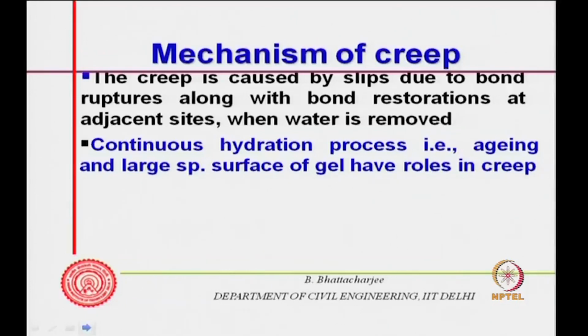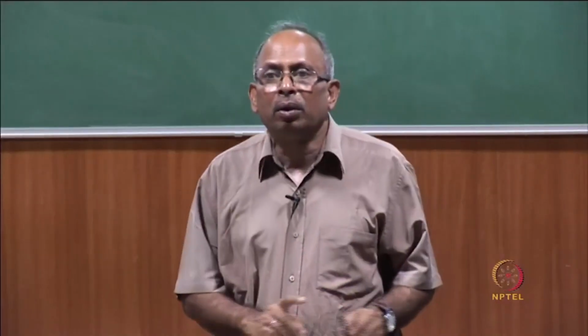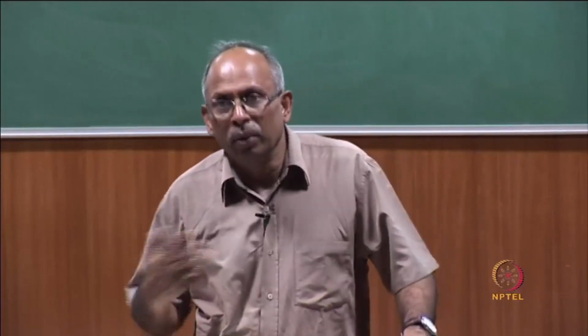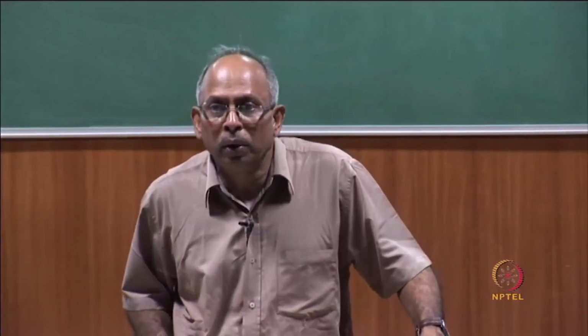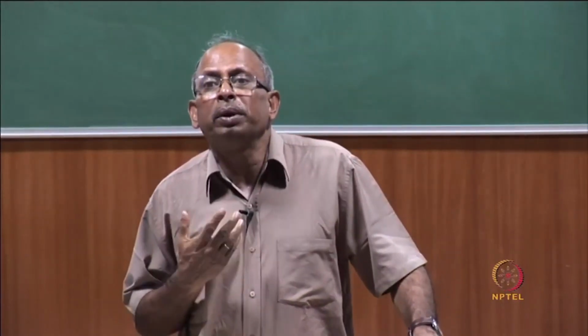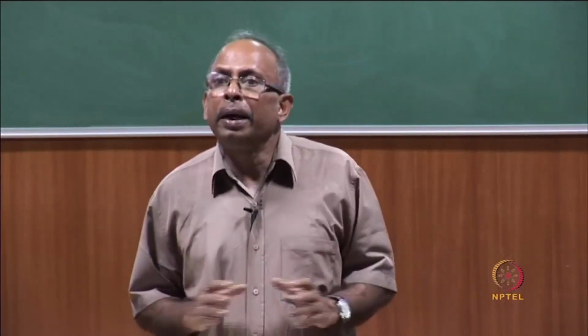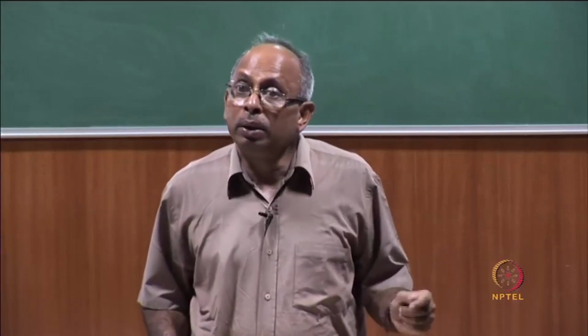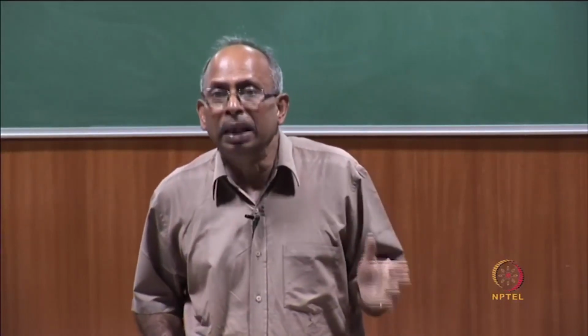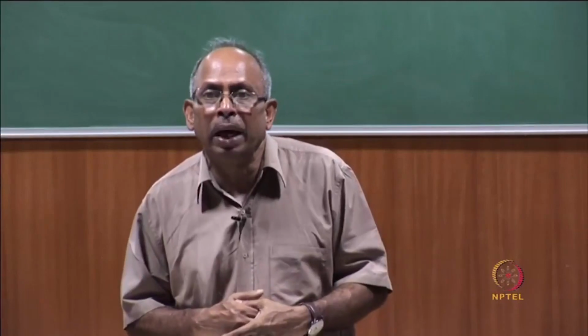But one has to remember that in cement paste or concrete, I am talking of cement-based concrete, the hydration process is continuous. It does not occur instantaneously and it goes on occurring. This is what you can call aging, the material changes with time.